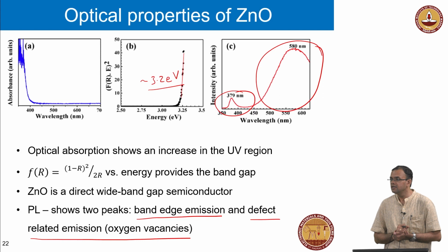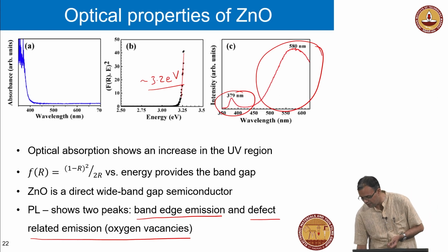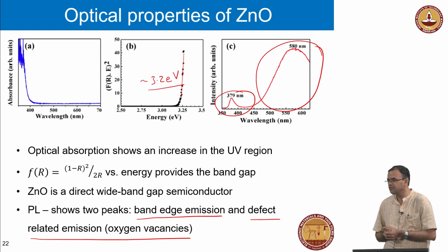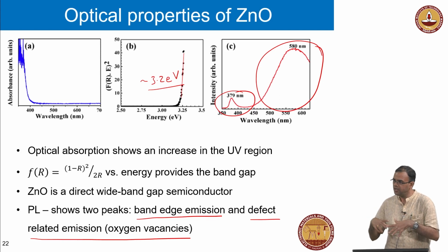How can we measure the actual electronic band gap? So, for example, let us say you have a material which you know is defect free, then your optical band gap is the same as the electronic band gap. That's probably one way to go about doing that. Any other way to measure electronic band gap? So I'm not sure. Yeah, that's another way. You look at how resistance changes as a function of temperature. From those plots, you can extract the band gap.